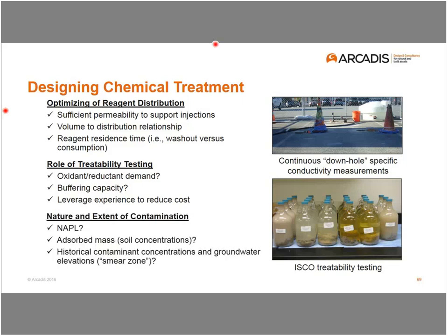And then lastly, the nature and extent, and this really gets at what Rick was hitting on with the LNAPL CSM, because when we're at a petroleum hydrocarbon site, it's more likely than not that we have residual LNAPL that's trapped. And it may not be mobile, it may not be accessible, but it's likely that our chemistry can change that very quickly. LNAPL can reside above and below the water table, as Rick indicated in the smear zone, and if we go after it with really aggressive chemistry, we might change its solubility, we might change its mobility, it might show up in locations where it hadn't shown up before.